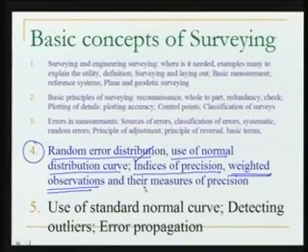Then the other thing, precision. We know precision is an indicator of the accuracy, provided we eliminate systematic errors. So if the precision of the data is good, we say our observations have higher weight, they are better. So what we did was, weight is inversely proportional to the variance, and variance is an indicator of the precision. Then we saw some measures of precision also for the weighted data. So this is all we have done so far in our last lecture.